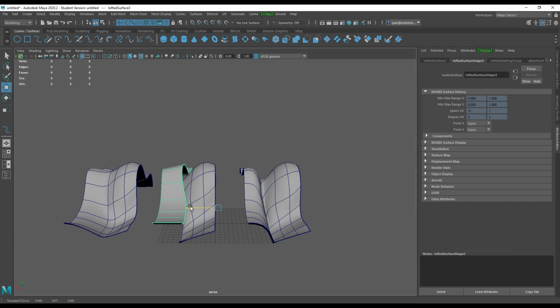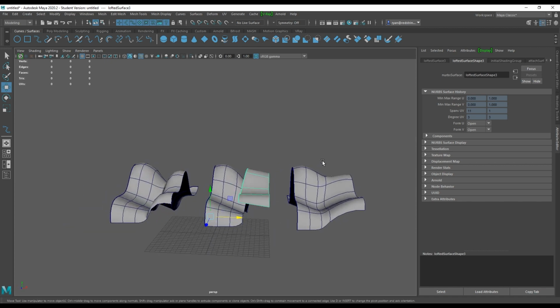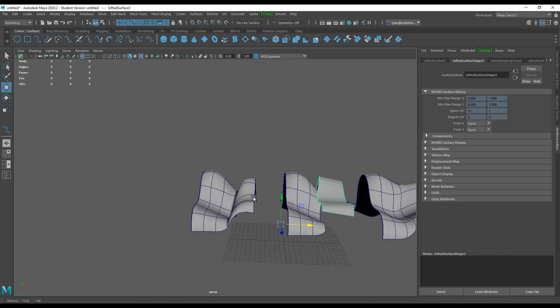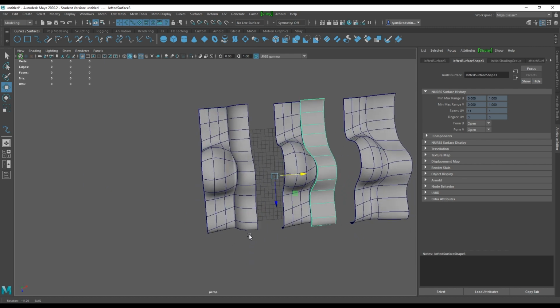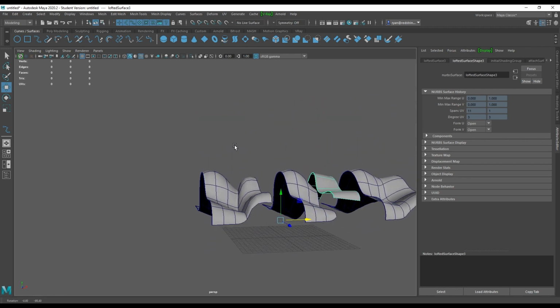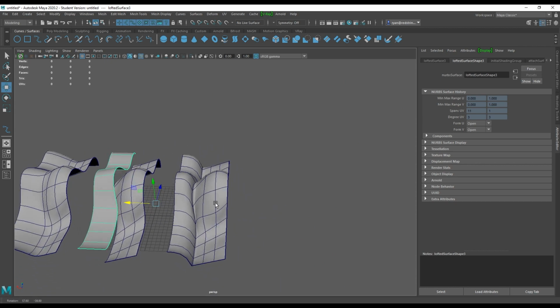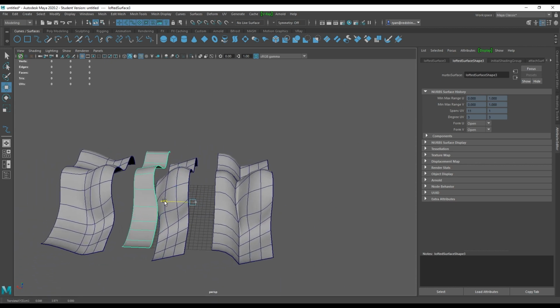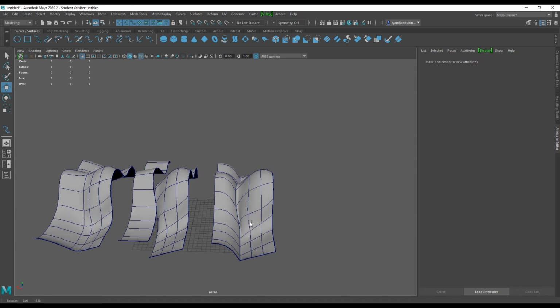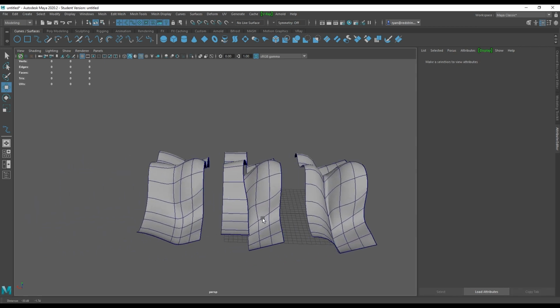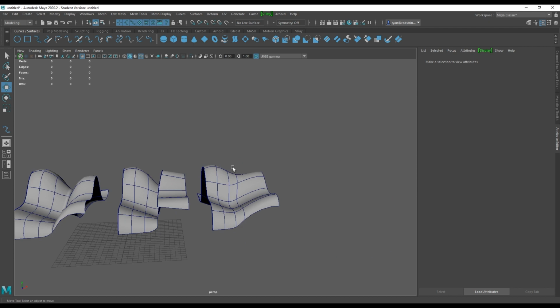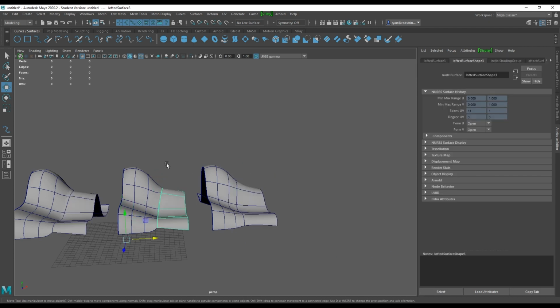So if I go here, you can see the blend one tries to keep a smooth surface. The just attach one is getting a sharp, crisp line. But as you can see, it's starting to collapse over itself, which is not ideal. I will potentially take it about here, for example, to get the attached one to look nice. Or if you want to just keep this one, you have the options to do so. So I'm just going to undo a few times.